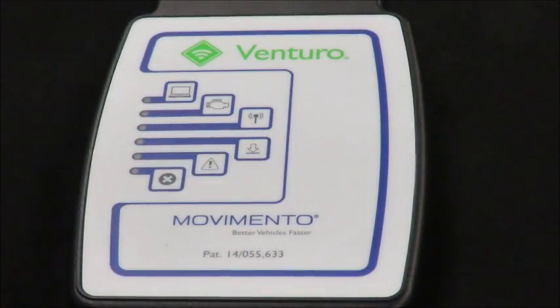The telematics control module is a conceptual IMX6 based processor product that represents a module currently designed into the vehicle. It maintains communications externally to the OTA cloud via Wi-Fi, Bluetooth, satellite, or cellular. Communications to internal modules would be achieved across current established vehicle networks, for example, CAN, LIN, or Automotive Ethernet. The OTA client software could also be a smart gateway module, head unit, or IVI system.